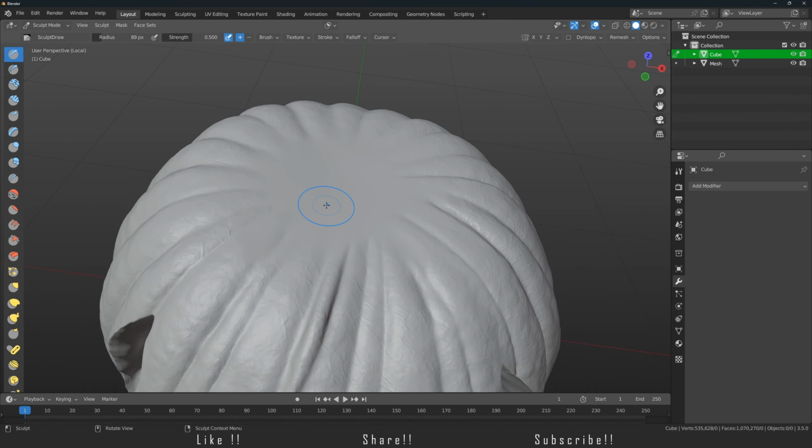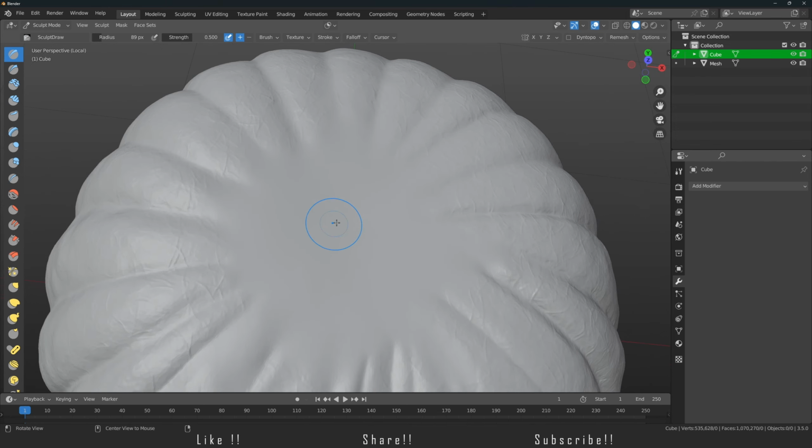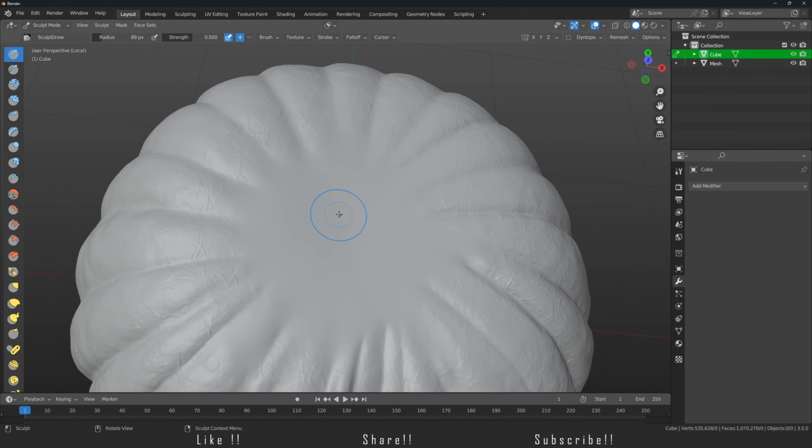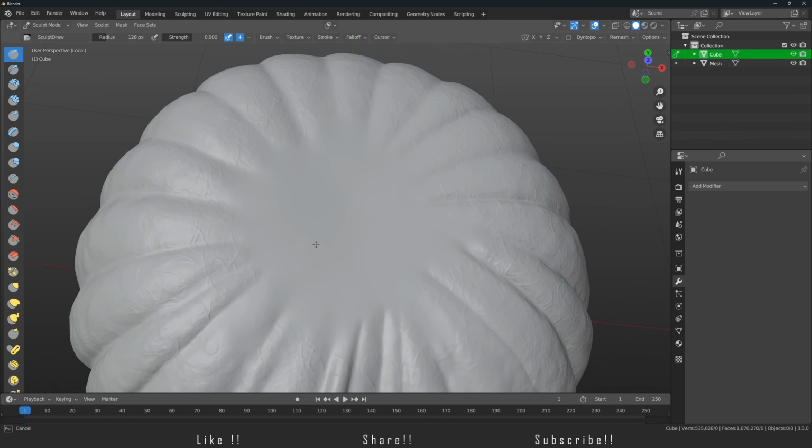They're going to touch each other, and if there are some weird artifacts, then there is a possibility that the keys are not going to be accurate, and even if they are super accurate, you're still going to see the gaps. So make sure that the surfaces on which the keys are going to be placed are super smooth.